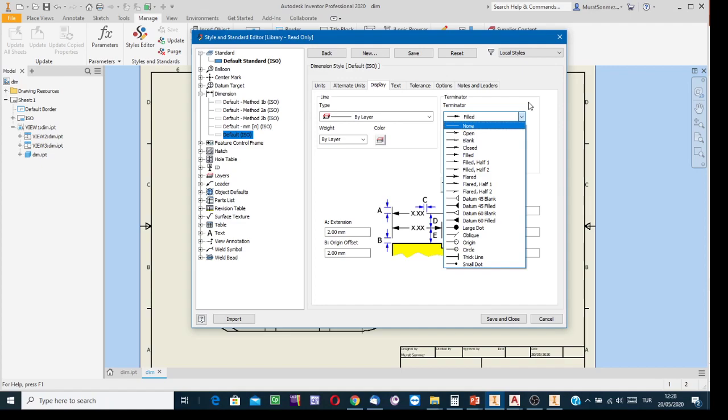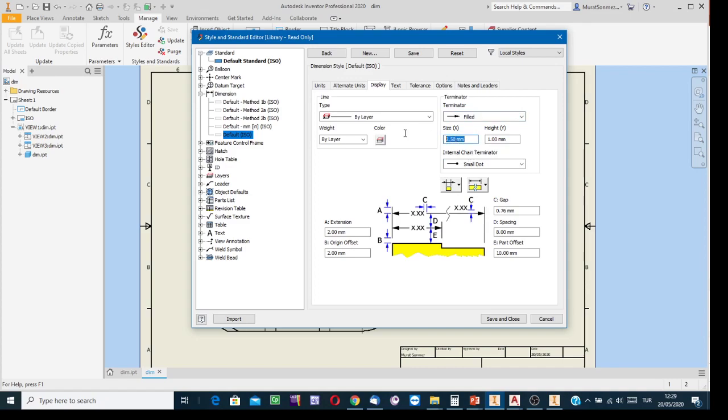Configuring the dimensioning facility for the other example, where I have the model of a building in plan view, I'm going to select this option. But here, since it's a machine element, I need to select the filled option. Arrow size for A3 size paper is 3, and the other size of the isosceles, the termination symbol, is 1.